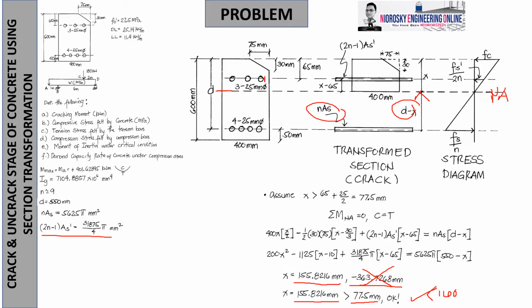Let's say, for example, it was not 160 but 165. What can you say? It means the assumption is wrong, so there should be a recalculation. Meaning, your checking was wrong. Okay? So, you have to recalculate your calculation based on your assumption. But usually, this will fall under a correct condition, because your steel is very close to the compression maximum fiber stress.